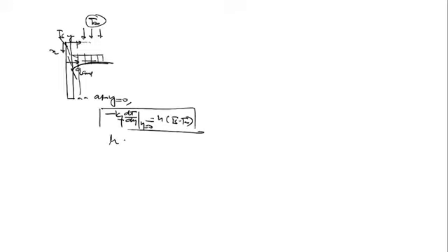So this is the y. Now this is x. At y equal to 0, minus k_f dT upon dy at y equal to 0 is equal to h into (Ts minus T infinity), and this h is equal to minus k_f into dT upon dy at y equal to 0, upon (Ts minus T infinity). Any problem, beta? But this is local. Why local? Because dT upon dy is going to change from location to location. Any problem?